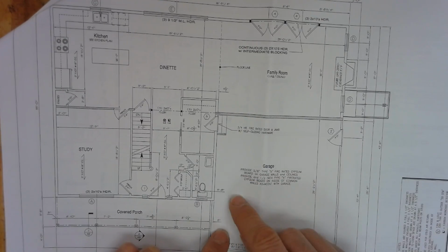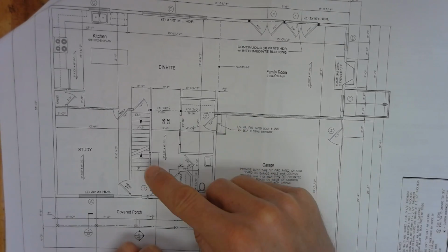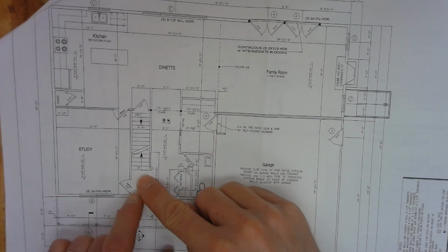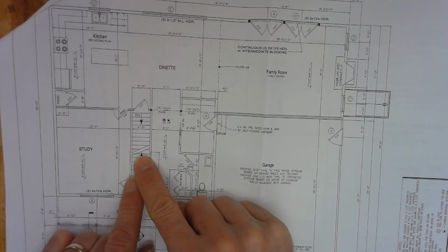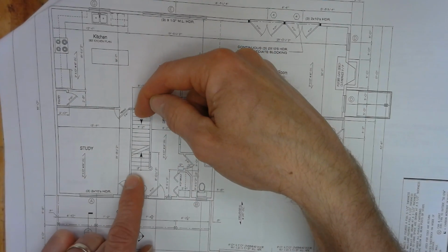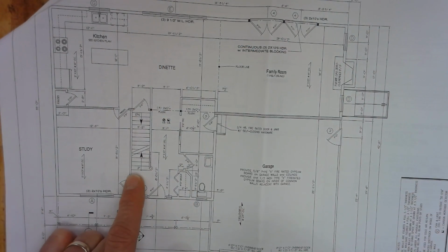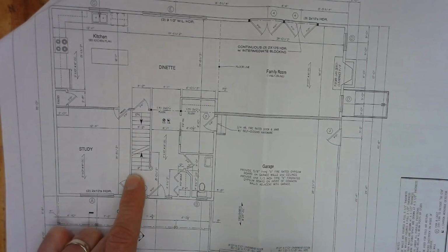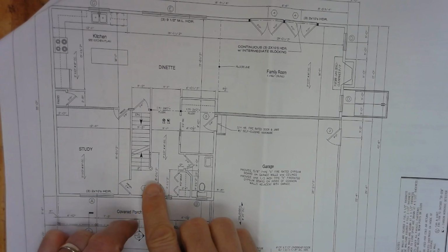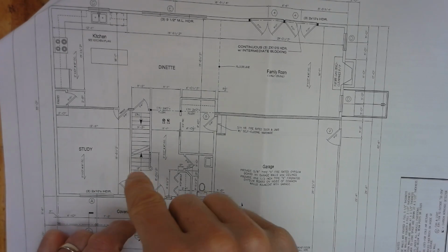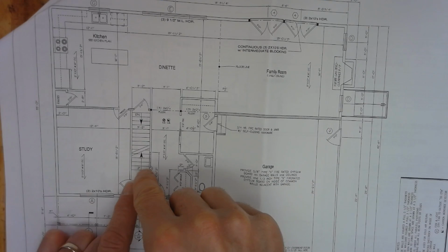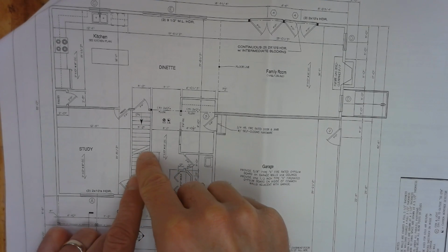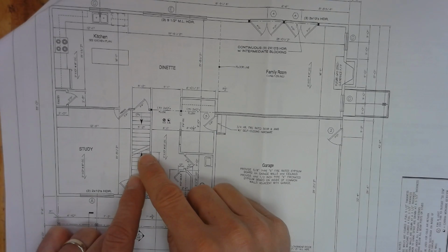There's the garage. This is how you enter. There's the stairs. Ooh, this is interesting. Here the stairs are going up, but here the stairs are going down. There's something about floor plans: we're looking down on the building, but we're looking about 4 feet off the floor. So think about this. In this situation, we're looking down, so we can see the first couple stairs going up, but then the rest of them kind of disappear over our head, so we can't see those anymore.